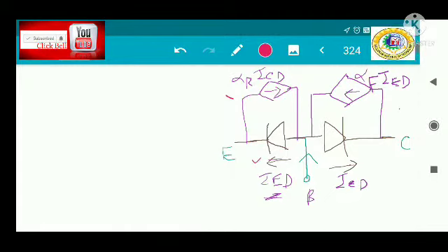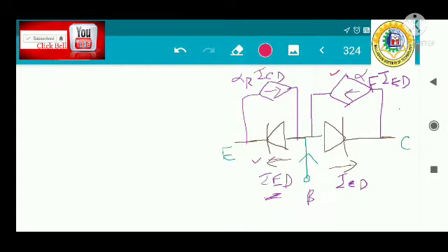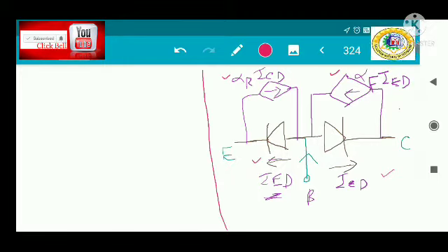These two are related. If we just reverse the transistor action, then some portion of the collector current, assuming the collector-base junction is forward biased, will be reaching the emitter, just the opposite action. So that's why this is the Ebers-Moll model.